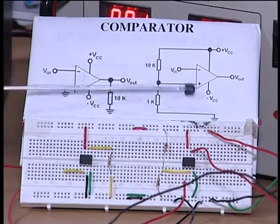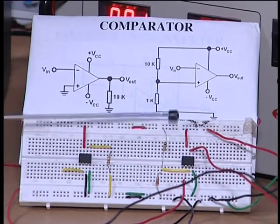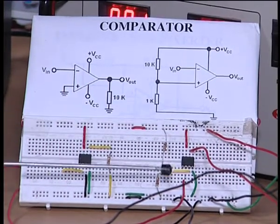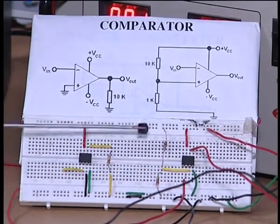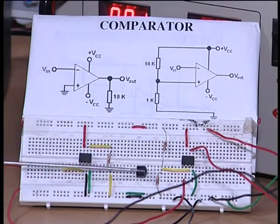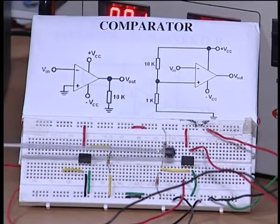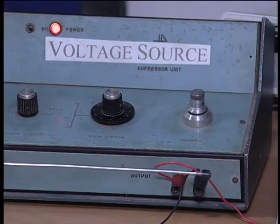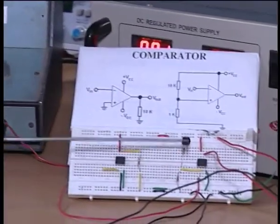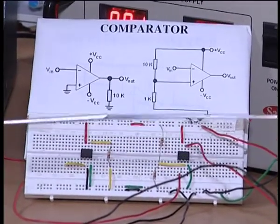Now, the same circuit is wired here. You can see the 741, and pin 7 is connected to the rail voltage, the plus Vcc, and the green wire corresponds to the minus Vcc at pin number 4. I have the potential divider, 10K and 1K, here, which is connected to pin number 3 corresponding to the non-inverting input, and to pin number 2 you see I have connected the millivolt source. This millivolt source's red line is going to pin number 2 in the circuit, and the output is monitored by this red wire, which is connected to a multimeter.